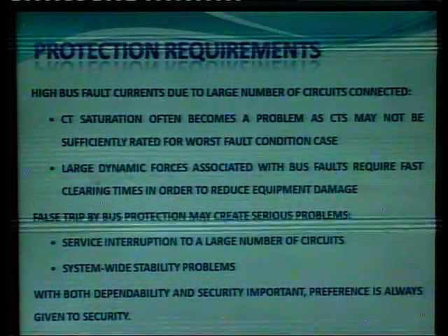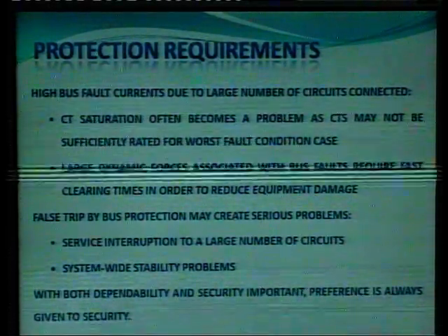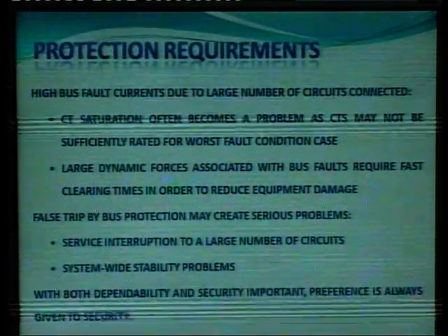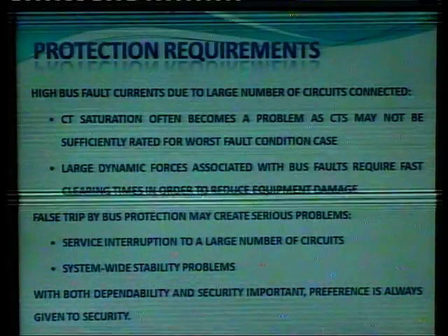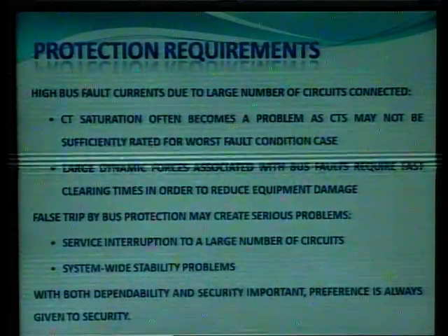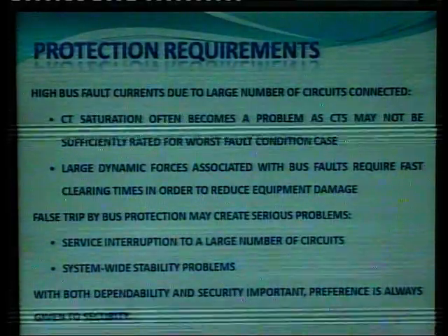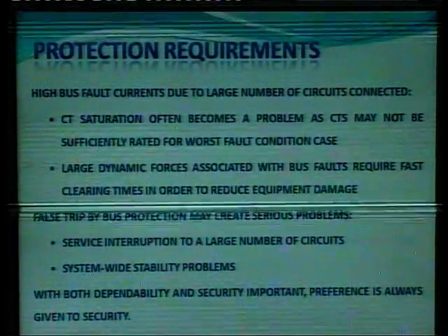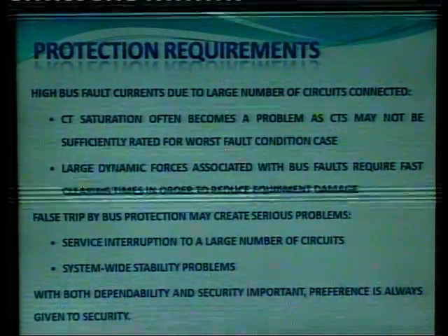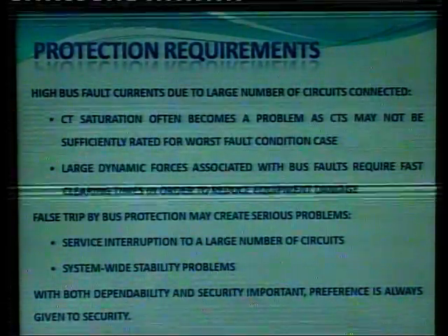So, second is large dynamic forces associated with the bus fault require fast clearing time in order to reduce the equipment damage. Now, a false trip by bus protection may create serious problems, which will cause service interruption to a large number of circuits and system wide stability problems. So, of both dependability and security, the important preference is always given to security.